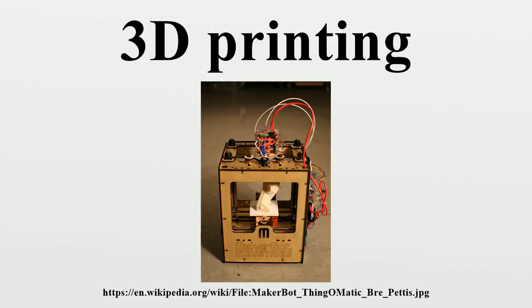Once completed, the STL file needs to be processed by a piece of software called a slicer, which converts the model into a series of thin layers and produces a G-code file containing instructions tailored to a specific type of 3D printer. This G-code file can then be printed with 3D printing client software.